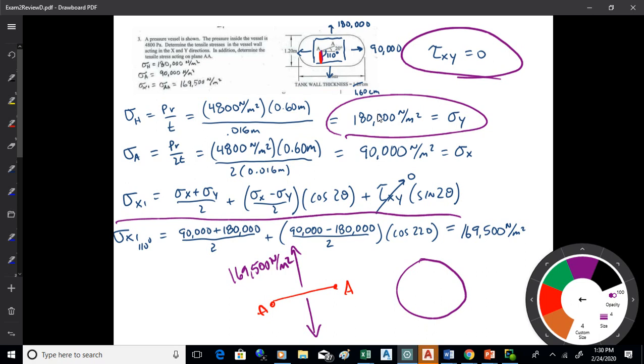It's a sphere because that way it's all axial. There's no hoop in a sphere, so it's built to contain more pressure because you don't have to worry about the hoop stress. You're just doing axial stress. All right with that? Good.